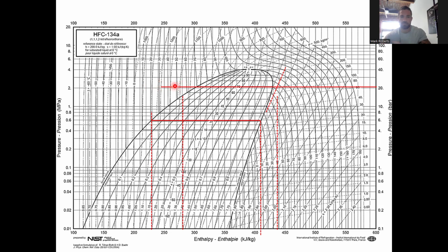So it cools to a saturated liquid or a cooled liquid. Then this liquid is sent through a throttle, and when we send a liquid through a throttle, some of it vaporizes. It's a constant enthalpy process, delta H is 0 through the throttle, until we get back down to the bottom pressure that we started at, the pressure that I fed into the evaporator.